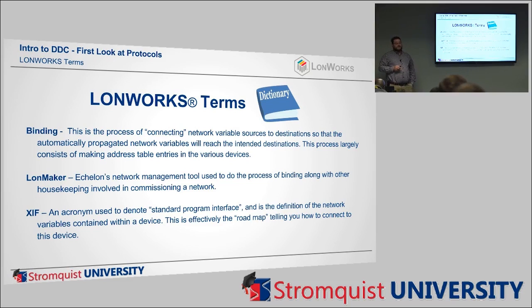Yeah, so a Niagara system is not flat LON. One of the definitions of flat LON is it's a pure LON system, and a Jace can do more than LON. But also, a Jace is more of a front end, and everything comes below it, where flat LON is everything's literally flat. There's no servers or clients. It's all one flat system.